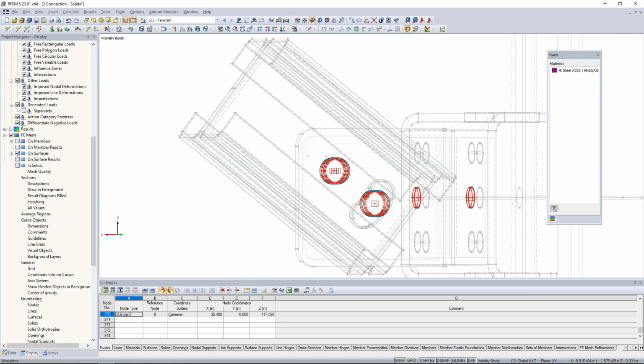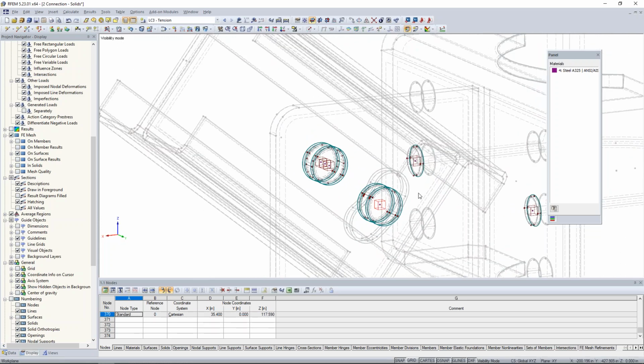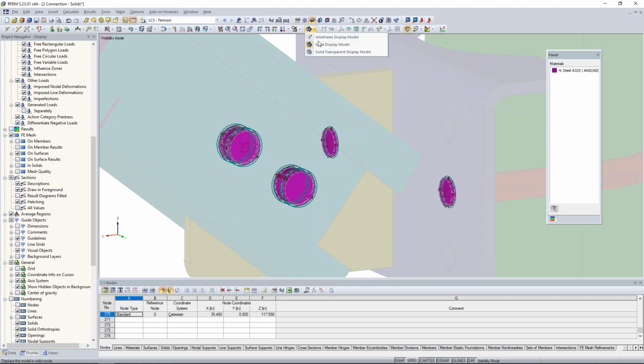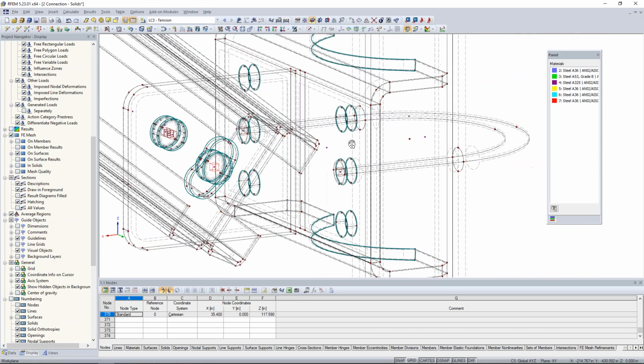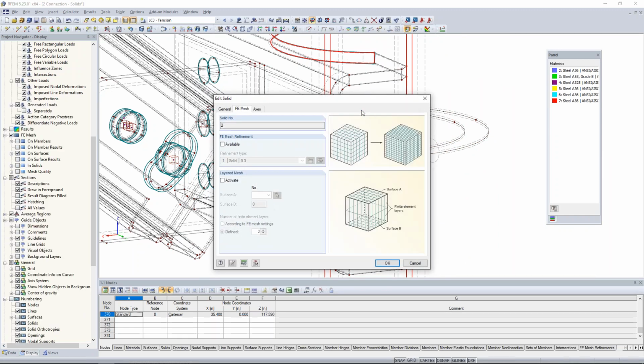Now, in addition to these smaller elements, and you can see the FE mesh refinement shown here with this cube type symbol, if I take a look by canceling my visibility mode here, and I look back at my pipe element, we actually can also use FE mesh refinements for larger FE mesh lengths as well. It doesn't necessarily have to refine it into something smaller.